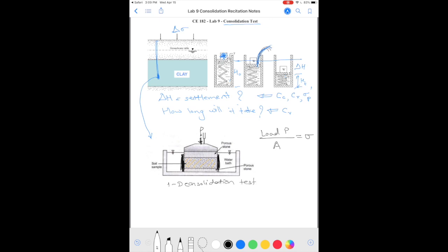Okay, which represents this schematic on the top, where we are applying some vertical stress uniformly across a soil layer that's uniform and extends infinitely on both sides. And in this case also the soil is going to settle only in the vertical direction. So the idea here is to change sigma, the applied stress, and keep track of the settlement.